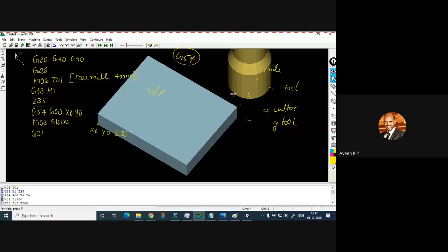See, now you can see the initial position of my tool, which is coming from G28, the origin. It is above the work part, and this is clearly visible. From this point to here, it is having the height of 35. It will come to the 0 0 position, above 35, and locate here. So this distance will be 35.